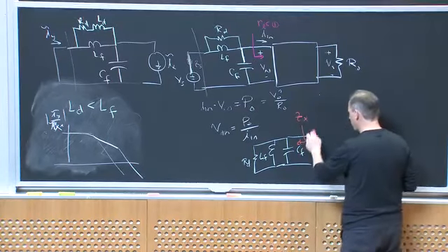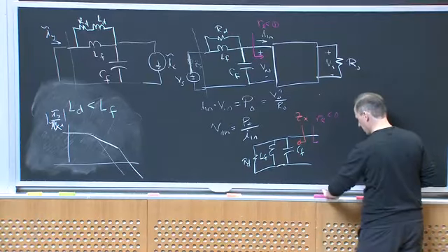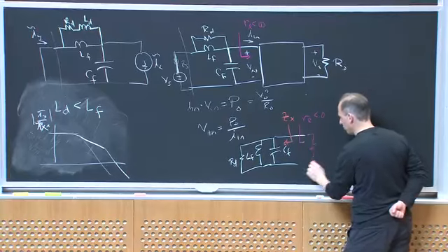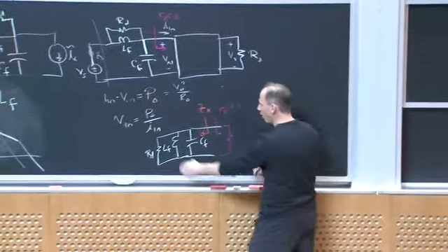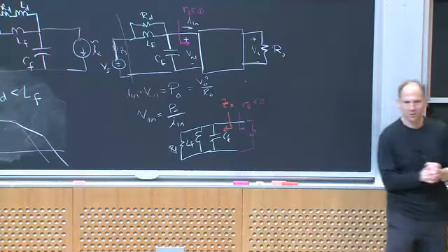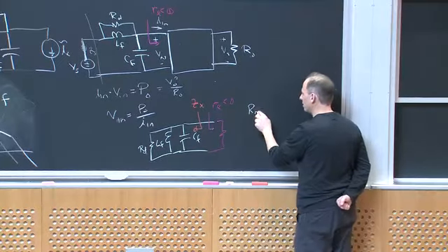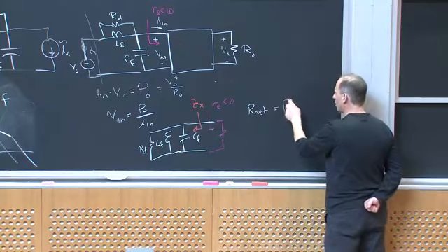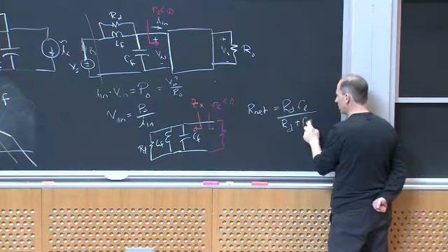And he's looking in the other direction. He's looking into R sub L less than 0, okay? And this is my converter and his load, in the case where the converter is perfect. All right? So what's going to be true? Well, basically, RD and RL in this example are in parallel, so the net resistance, R net, the effective resistance damping the LC tank, is equal to RD RL over RD plus RL, right?